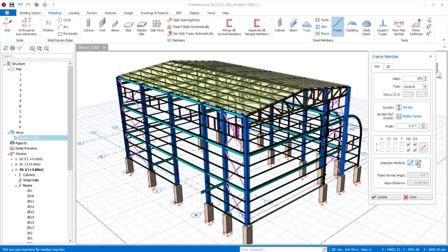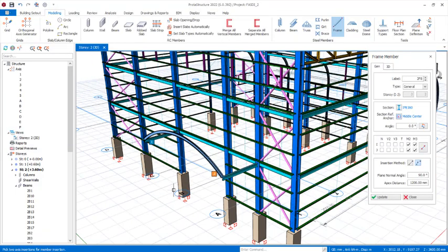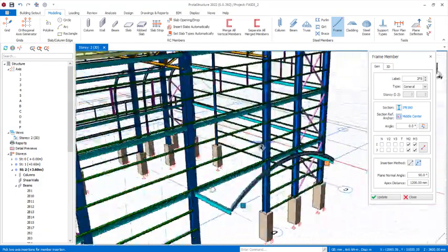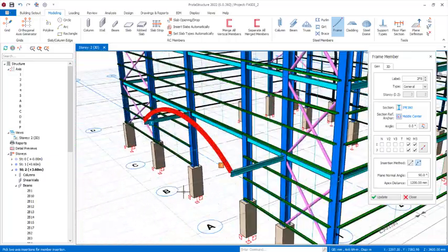Okay, so I click on this curve construction method. I will also use 90 degree. Then I will consider it to be 1200 millimeters, the radius of the curve. So I pick this point first, come all the way, pick this other point to place the curve just like this. All right, so this curve, let's say the radius is not too deep.